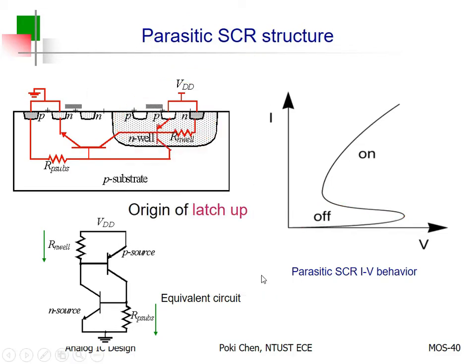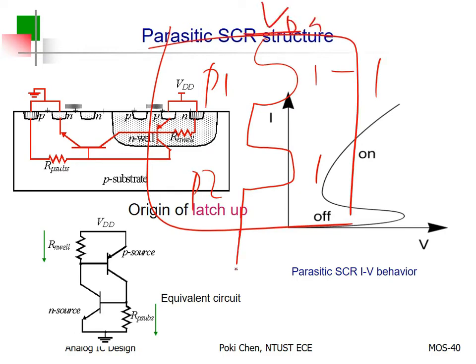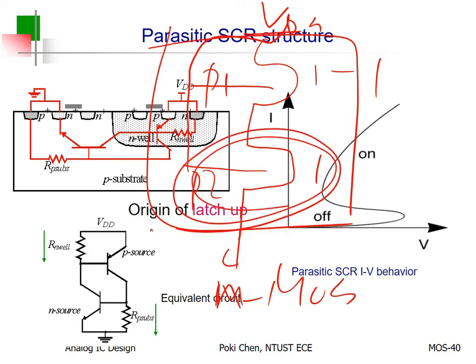But, for example, if you have such kind of, nothing is free. Okay? You have P1, you have P2. Usually, if you put P1 and P2, this is VDD. And that is PMOS. Usually, if you put P1 and P2 inside the same N well, because your body and his body should be exactly the same N well, then connected to VDD. Then P2 needs to face some of the body effect.